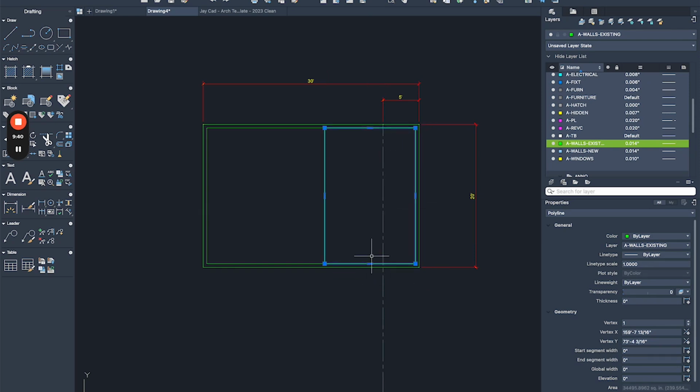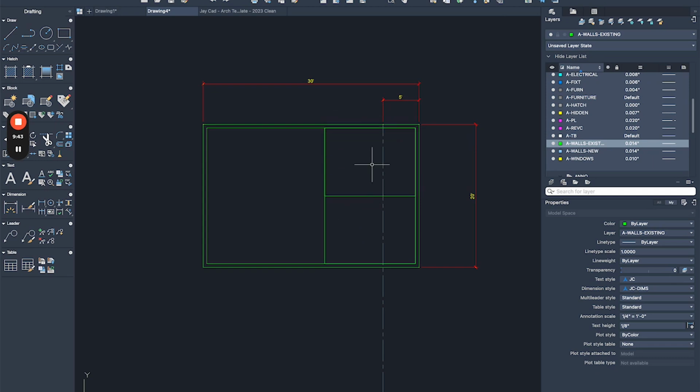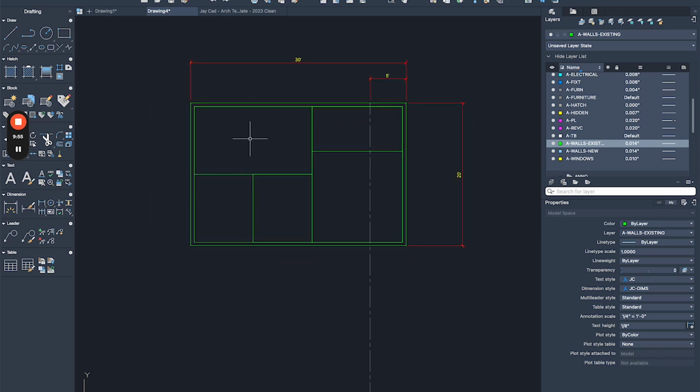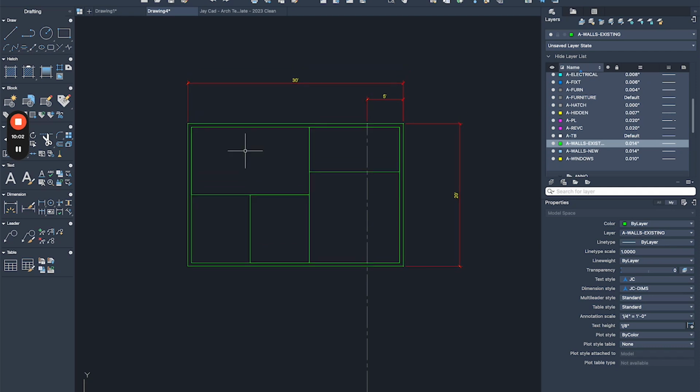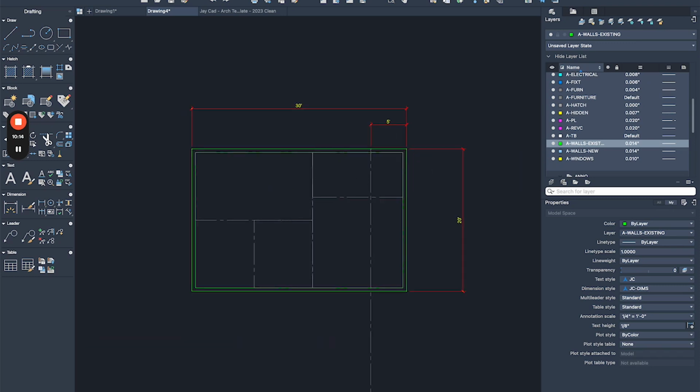Okay, so this is like something like this, something like this. This is gonna be the bathroom, the bedroom, and then the kitchen potentially in this area, maybe dining within this corner. So this is kind of the ratio of how things are going to look like. Can make it smaller. I'll make small adjustments as we go to make the design work better, but for the most part, this is where I'm heading with this. I'm going to use the match properties command, so I can keep these boxes as references here as well, and I'll continue with the ray command.